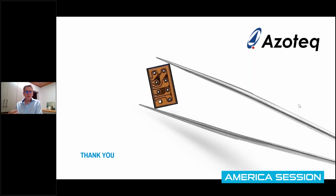But otherwise, we've done concepts where we use a small surface mount component. That literally consumes a space of less than 1 millimeter by 1 millimeter on your PCB. Then your conductive coil is turned in the Z direction, and that consumes extremely little board space. So very suitable for a wearable.